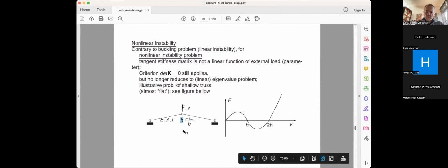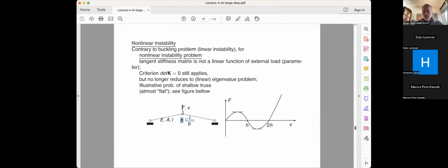And then you go further, you keep increasing the displacement, you come to the value 2H, then you realize what you have is the truss which is turned now upside down, and you can say that the measure of the deformation is a stretch. All the other strain measures are computed from the stretch. In particular, Green-Lagrange is 1/2 (lambda squared minus 1), where lambda is the stretch. So if you take L, phi, and L to be the same, the stretch is equal to 1. Obviously, lambda squared is 1, minus 1 is equal to 0. So I don't have any deformation.